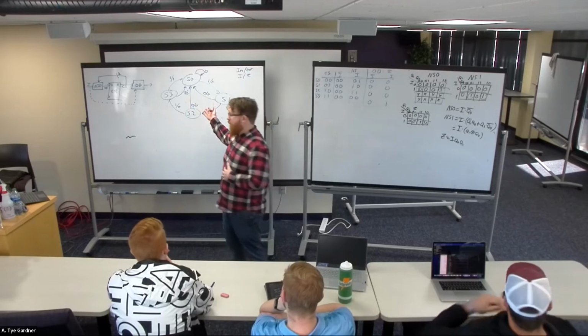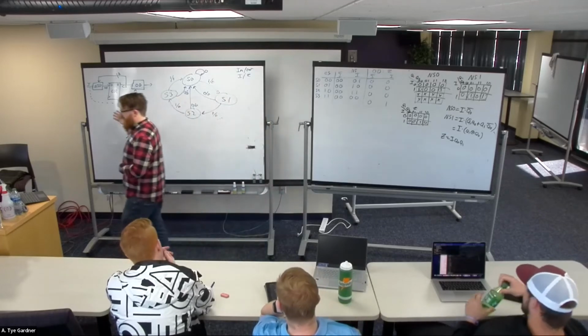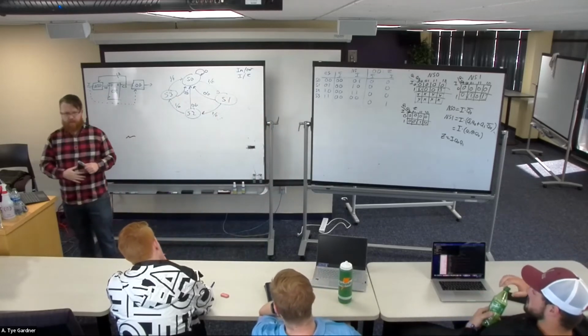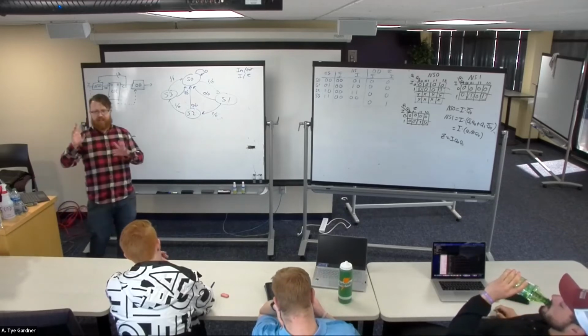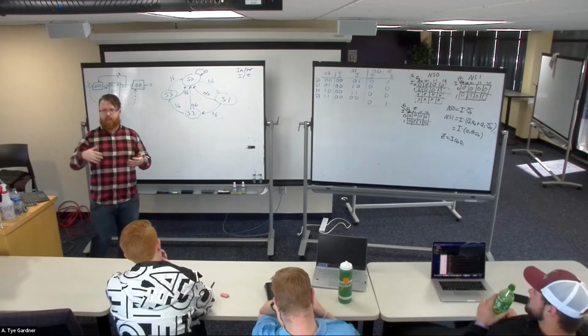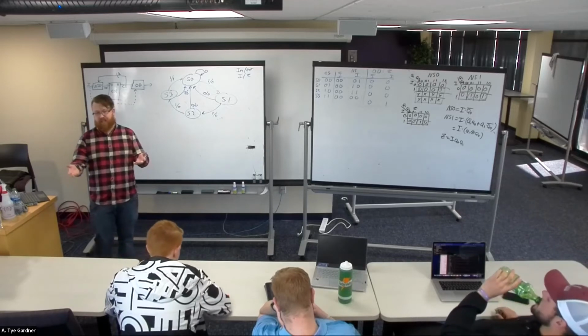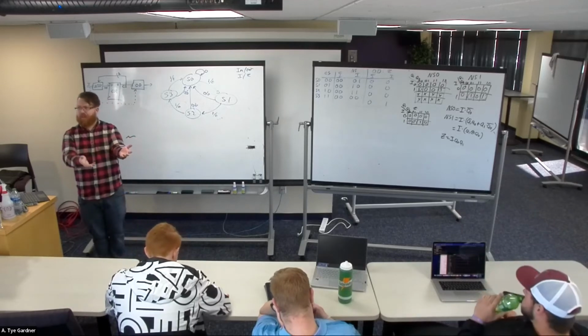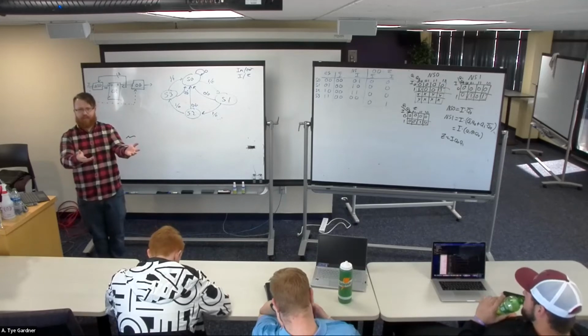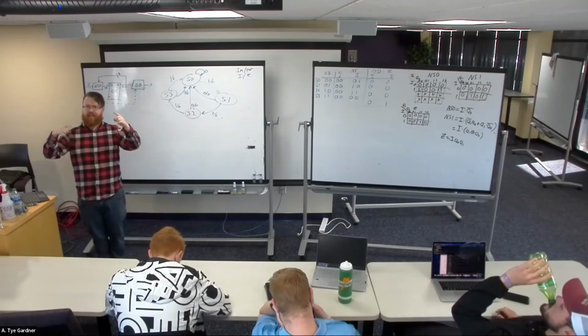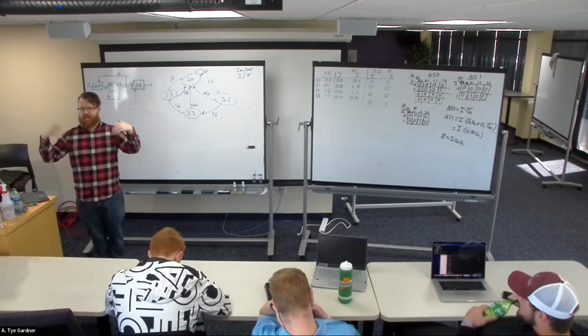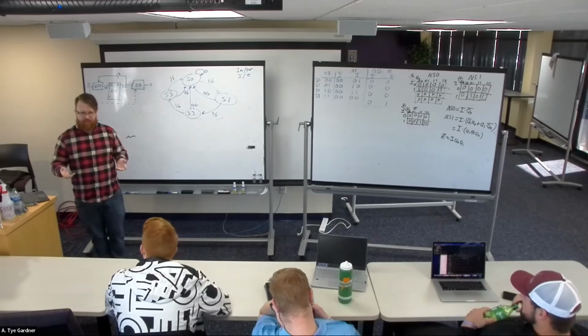Now, we could make up applications like this. In fact, we do something like this in some biological applications, because it turns out your body doesn't like to have standing voltages in it. So if we build prosthetics, for example, and install them in the body, we don't like long streams of ones, because it starts building up too much potential that can damage the circuit. So we design circuits that are intentionally flipping zeros and ones, even if they're supposed to be a long string of ones.